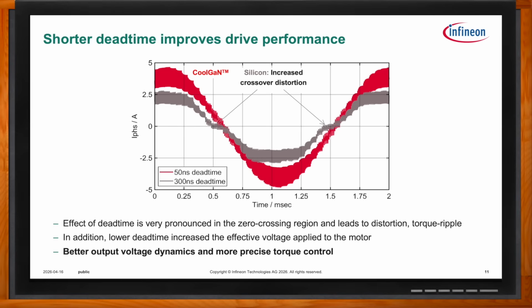Just a reminder, in a given phase of the three-phase inverter, if I shut off, say, the upper transistor, I can't immediately turn on the lower side, right? I can't do it half a nanosecond later. I need time to make sure that the transistor really has fully turned off. And there are also propagation delay variances between different gate drivers. So I need to allow a few nanoseconds, maybe 5 nanoseconds, just to make sure that the gate driver speeds aren't overlapping with each other. Then I can turn on the low side.